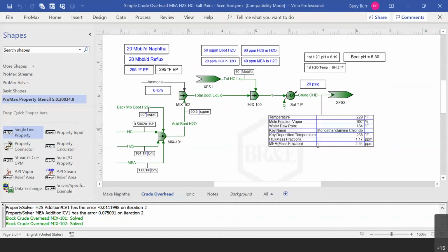We could do that, but in almost all crude units I've seen, I just never have seen predictions of second liquid phases forming on the stages. There are probably other forms of corrosion that occur on these stages, and maybe there are issues related to entrainment of water that we're not capturing in our separators, which assume no entrainment unless you impose it.